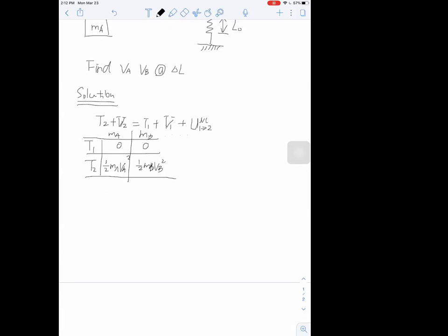But the next step in your solution is you need to find all the work done by the forces in your free body diagram, right? And so the work done from 1 to 2 by all the forces. Then if any force is a conservative force, then you can write that work as the potential energy at endpoints as V1 and V2.